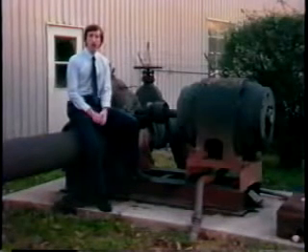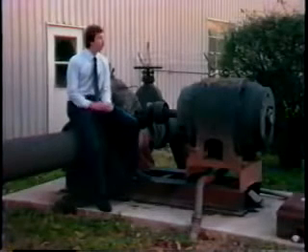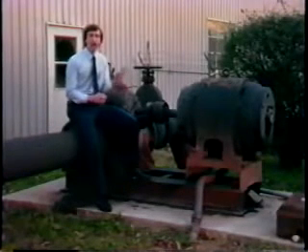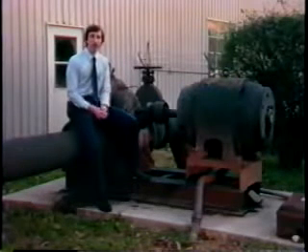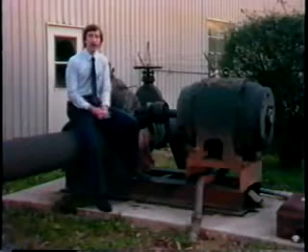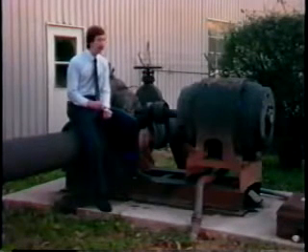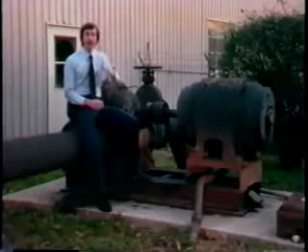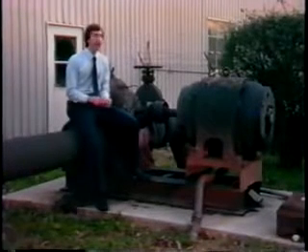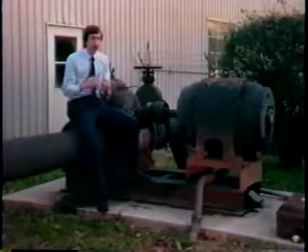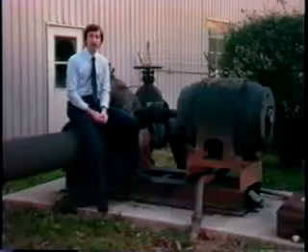Also, you'd like to know what kind of pressure is being put out by the pumps during the test. In particular, you want to be sure that the pump isn't dropping its pressure when you open up the hydrants. For example, if a pump is already pretty far out on its head characteristic curve and you open up the hydrant, what's going to happen is that the pressure at the source will drop. Now, if you did not know that this happens, you might think that the distribution mains were losing their carrying capacity when really you were overtaxing the pump that was on.